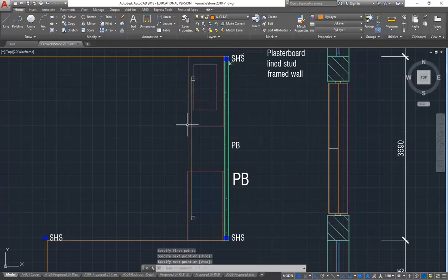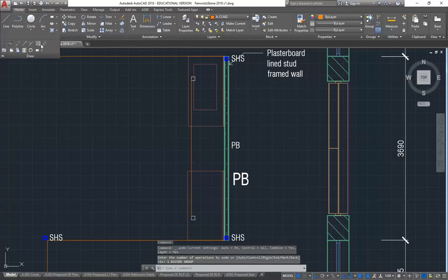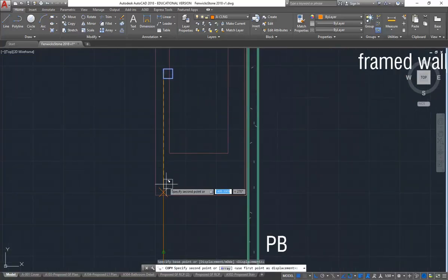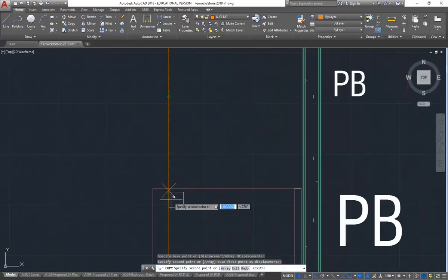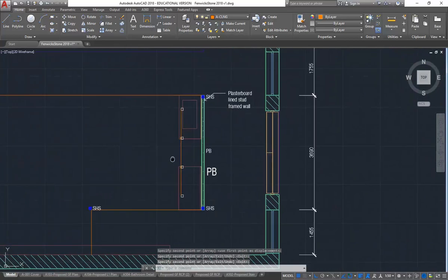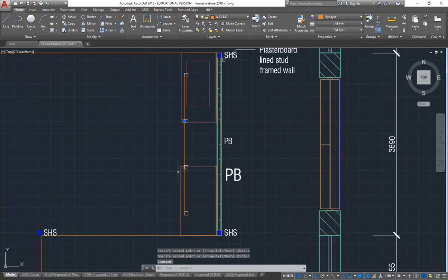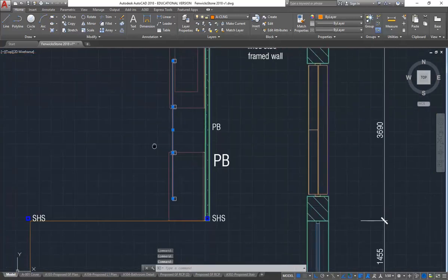Again, using construction lines like that, you can use tools that you've been using before, like divide. So there, I'll make that have 4 segments, and in fact, sorry, that's too many. I'll do 3. Okay, so then I can copy my light, snap into those points, placed more accurately. And then I can delete the construction lines.